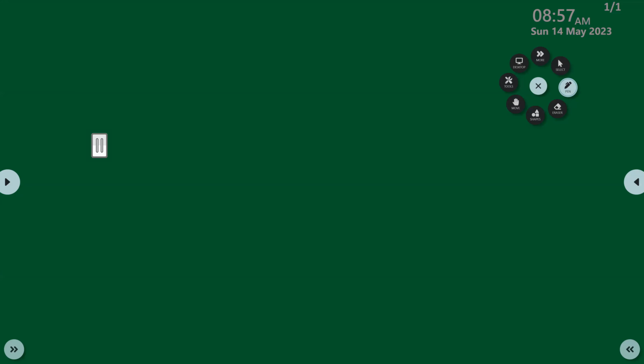Before designing anything, you need to define the functionality. Let's say you want to design a flip-flop; you should know its functionality. Let's say you have a flip-flop with D, Q, clock, and reset. You need to decide the functionality of this flip-flop. Let's say if reset equals 1, then Q directly becomes 0, irrespective of the clock, D, anything. That is my requirement.